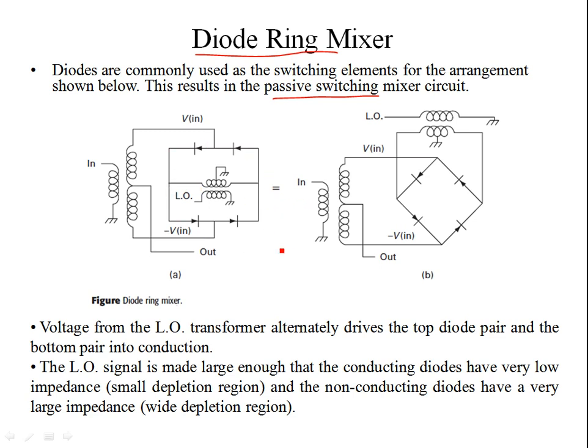It looks like a bridge rectifier, a full bridge rectifier. In the second configuration, you can see the way these diodes are connected, it's P to N, P to N. It's one and the same configuration with the local oscillator, the same node, the center tap transformer. Current or signal is being applied at the center of this bridge circuit. These are essentially the same nodes.